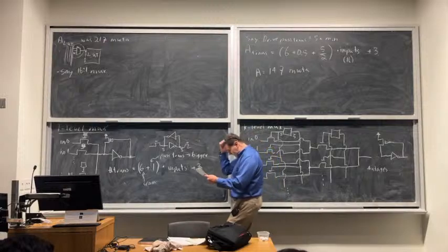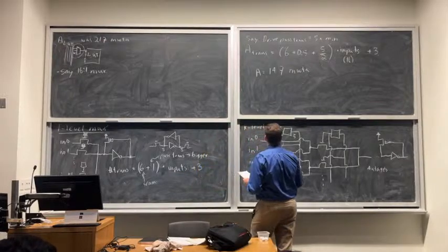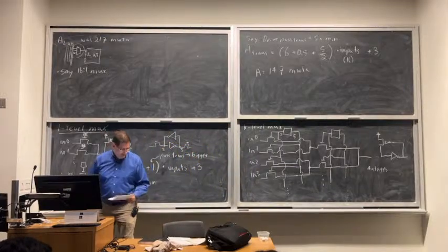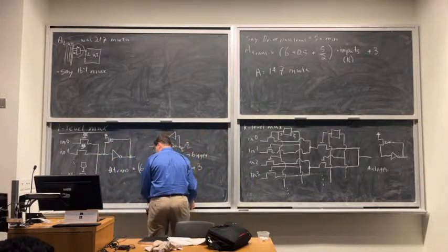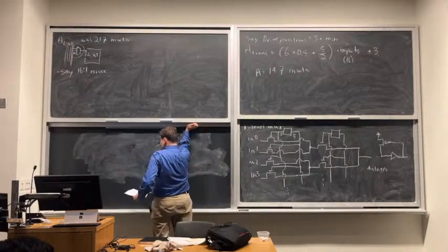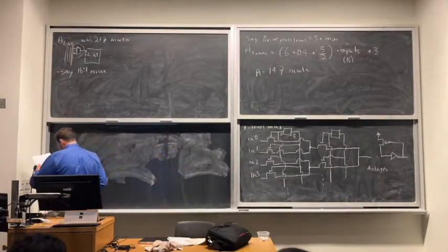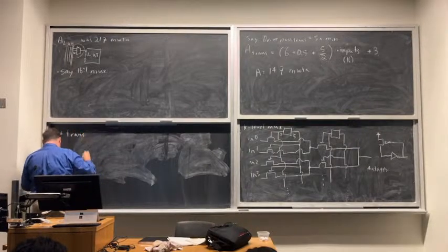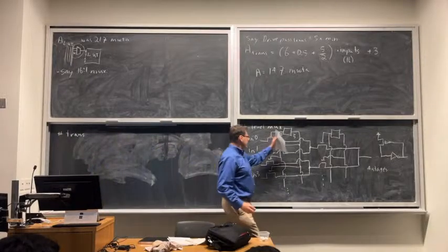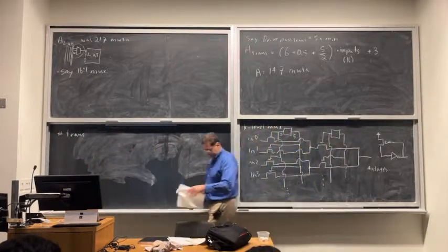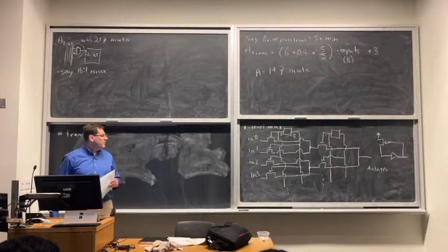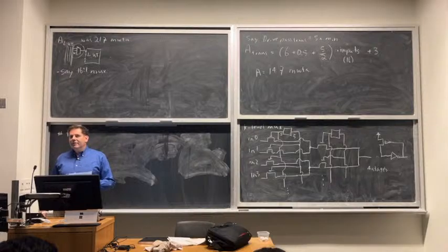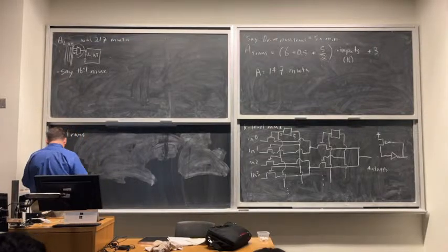So let's count what the area of this is. So we want to remember that 147. Okay, that's the number to beat. So let's see if I can erase something here. Maybe this can go up. Okay, so number of transistors. So how many SRAM cells do I need for some number of inputs? This one was 16 inputs. But in general, how many SRAM cells do I need? Yeah, so I need log 2 of the number of inputs.